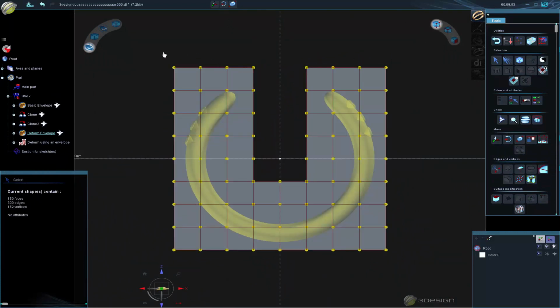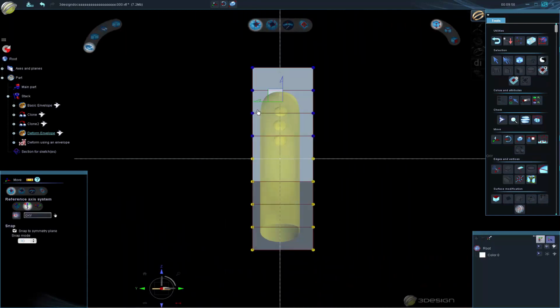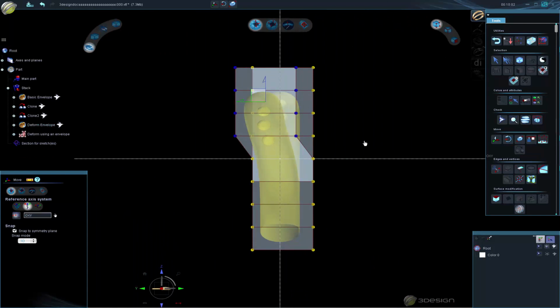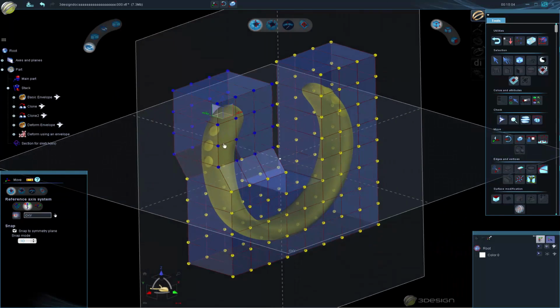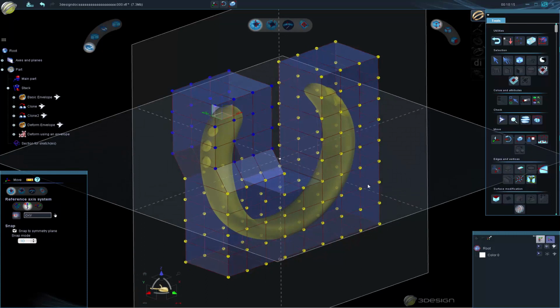Oops, make sure I'm in point mode. There we go, yay. Okay, so I've set it up properly. You see that my pave is linked to that surface, and we told it not to deform the jewels, so I can move my surfaces around, deforming the surfaces, and my jewels stay round, they stay in those positions.